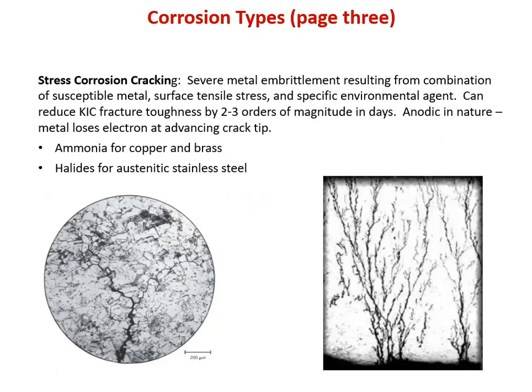Speaking of deadly, this is probably the worst thing you're going to encounter. Stress corrosion cracking. And if you have already had the lectures or read the topics under material failure, this fits in with the concept of fracture and your K1C fracture toughness. So if you have studied that, you'll know that the toughness of a material is going to be dependent on a material constant and the length of pre-existing cracks.